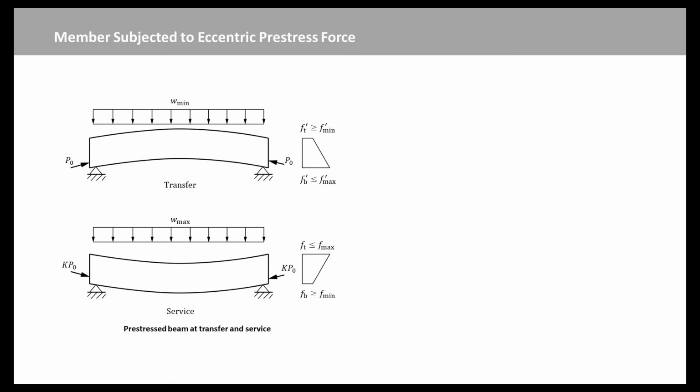The design of a pre-stressed concrete member is based on maintaining the concrete stresses within specified limits at all stages of the life of the member. Hence, the primary design is based on the serviceability limit state, with the concrete stress limits based on the acceptable degree of flexural cracking, the necessity to prevent excessive creep, and the need to ensure that excessive compression doesn't result in longitudinal and micro cracking.